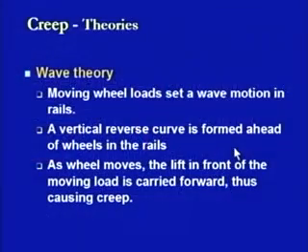And then as the wheel moves, this reverse curve, which is there in the front of the moving load, will be carried forward. Now, when this reverse curve is being carried forward, it will cause the creep of the rail, because the rail will start trying to move in the forward direction, and this is what the wave theory says.